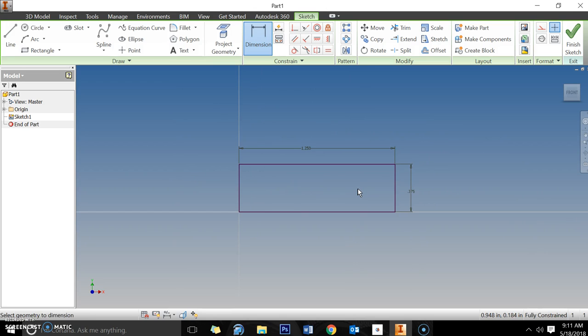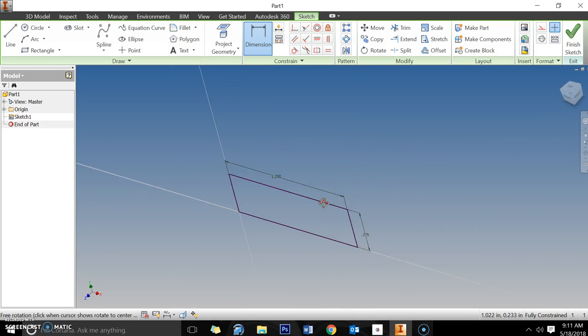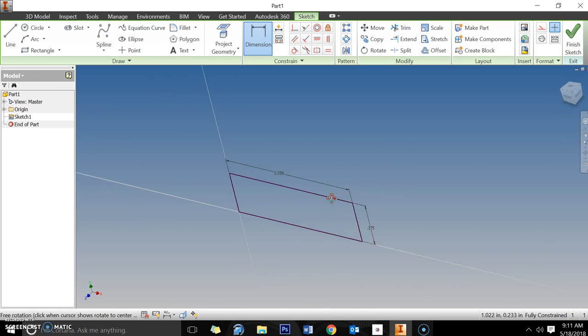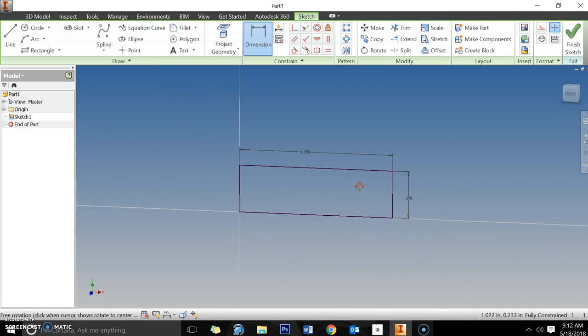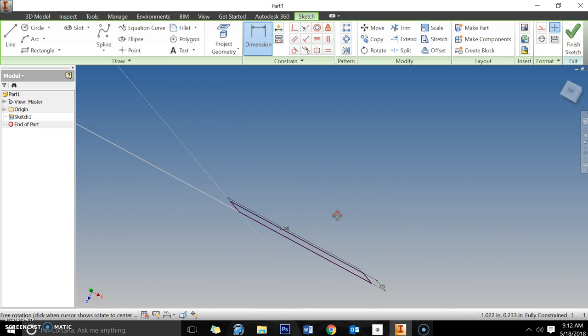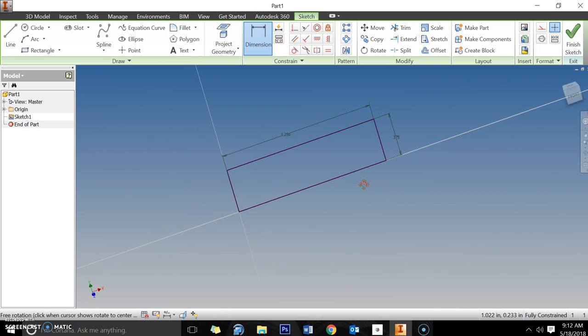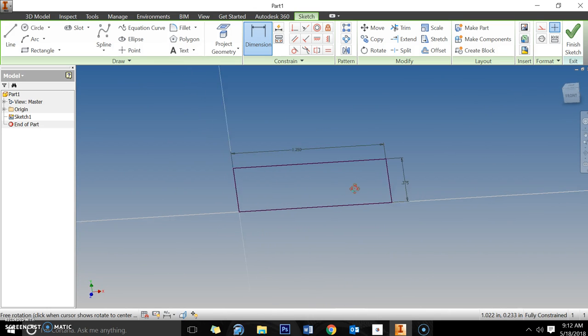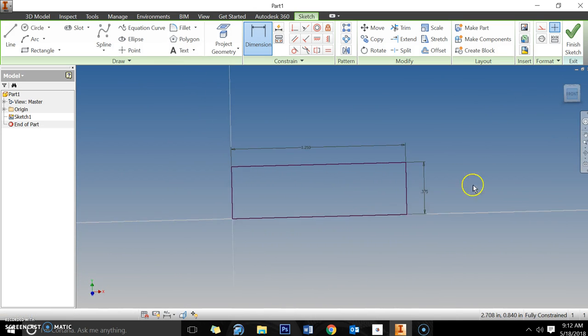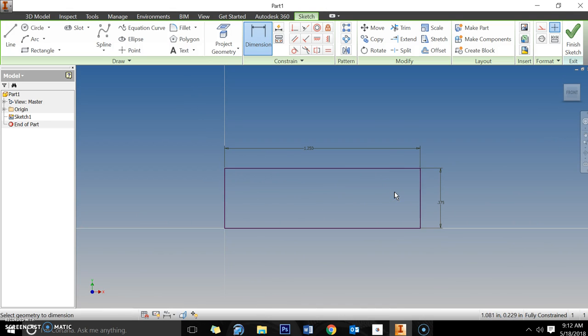And there's another one that you could do, called Orbit. So if you hold Shift and the center mouse button, I get an Orbit tool, and notice the view cube up in the upper right hand corner. See how it has front view listed, but I can orbit now. It has the top view highlighted, right side view, so I can get these different views. And that's not a big deal right now in the 2D world, but once we start putting some 3D features and things on this, that's going to be big. So I'll show you that here once we start doing that.